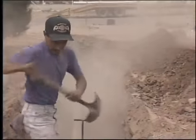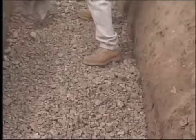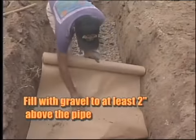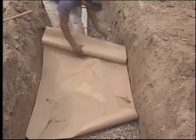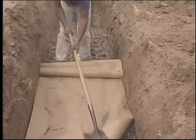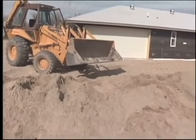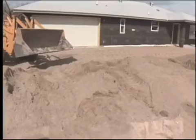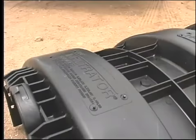Carefully cover the pipe network with additional washed gravel or approved aggregate to a depth of at least 2 inches above the top of the pipe. Next, place a backfill barrier such as a synthetic fabric filter or 4 to 6 inches of marsh hay or straw or untreated building paper over the gravel cover. Backfill to 6 inches above ground level. This completes your traditional gravel and pipe drain field.